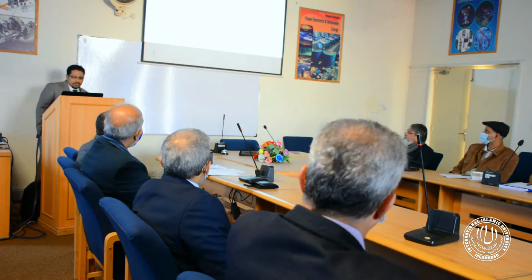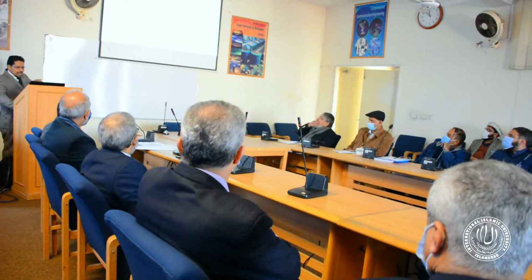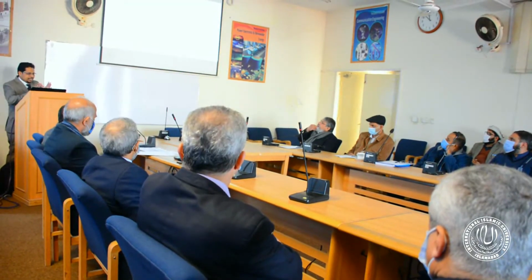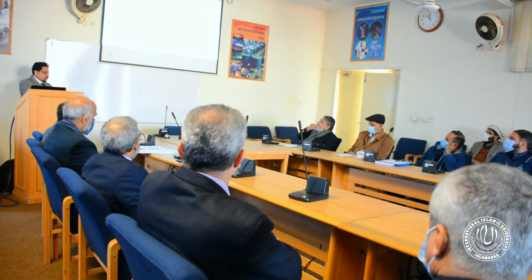So here, we can see that R is the range of the target as in equation number 15, and we can see that frequency 1 and frequency 2 are shifted in their Doppler as shown in equations 16 and 17. So the Doppler frequency components of the two received signals can be calculated as shown in equations 18 and 19. And these modifications are not yet in the thesis because we modified them based on the reviewers who asked for that after acceptance.